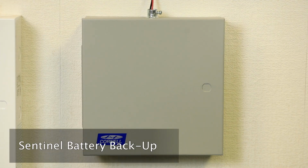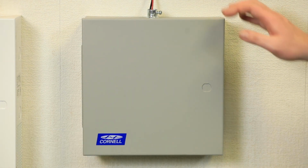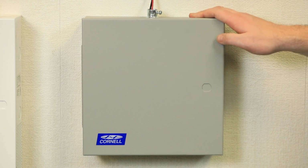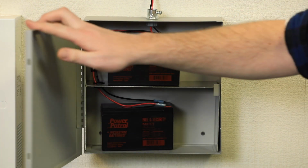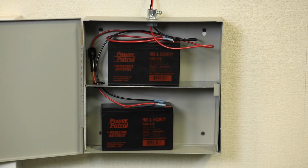Lastly, we're going to cover our battery backup options for the main head-end unit. We have 2 battery backup options. This one would be our smaller battery backup option, which includes a pair of 12 volt, 7 ampere hour batteries. It typically provides up to 3 hours of battery backup time for the main head-end unit.